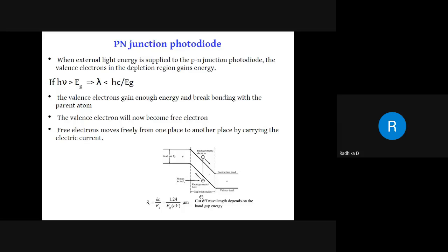But when a valence electron leaves the valence band, it leaves a hole; the absence produces a hole. So basically, when this light has fallen on the valence band in the depletion region, you have produced new electrons in the conduction band and new holes in the valence band. It has resulted in electrons and holes. For one situation, I can say there is a pair of electrons and holes being produced. Okay. Now, what happens next?